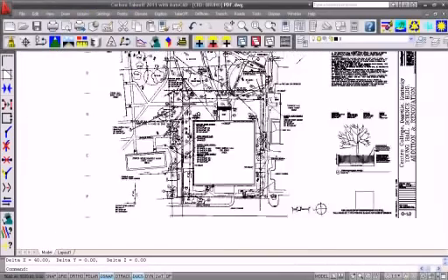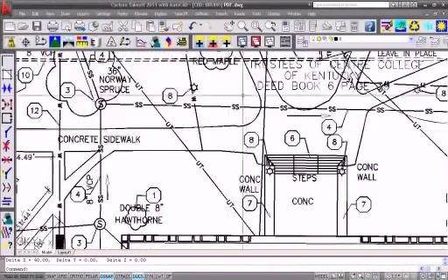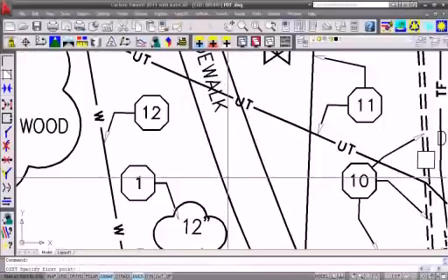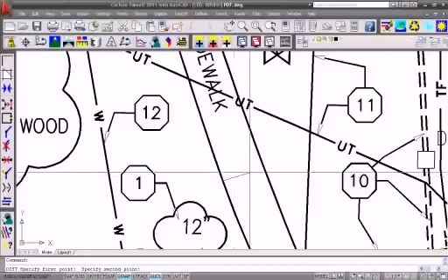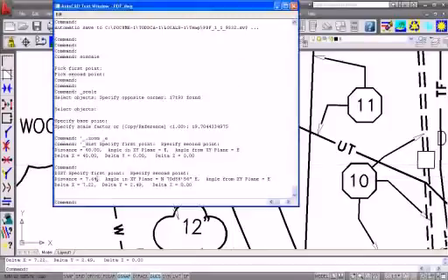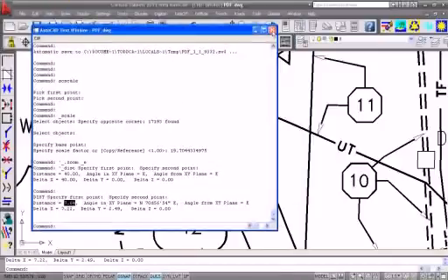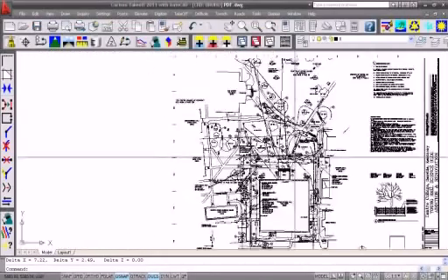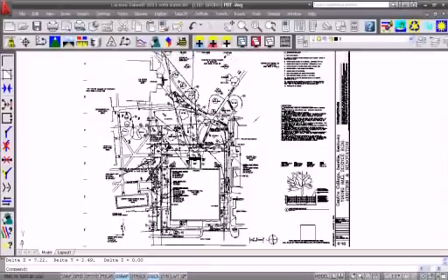If I want to check the distance actually on the job, let's go back to our asphalt block. Standard distance again, going across here, F2. Now that's over 7.5 feet wide. Makes a lot more sense for a walk as opposed to under half a foot. So we've now scaled this PDF accurately.